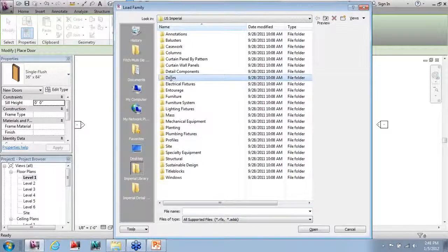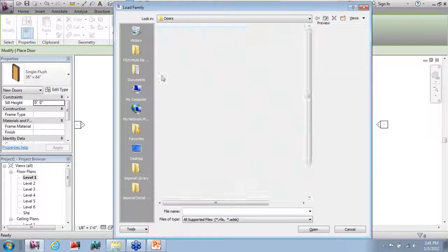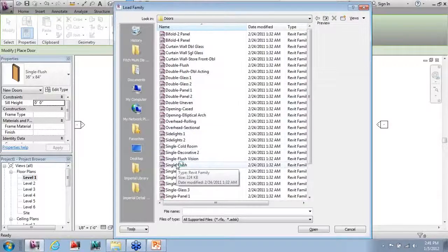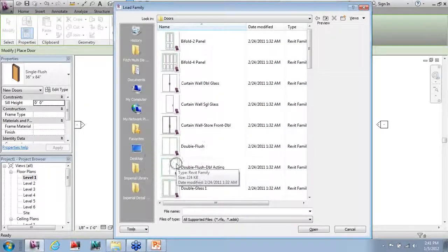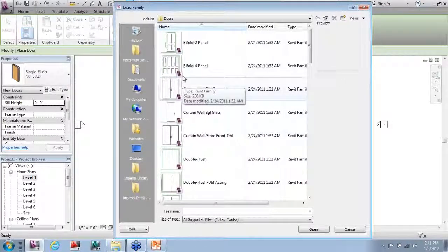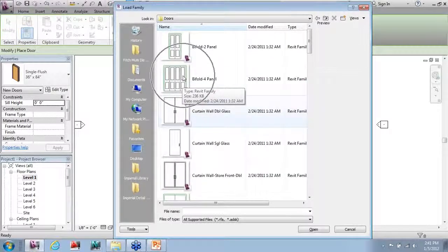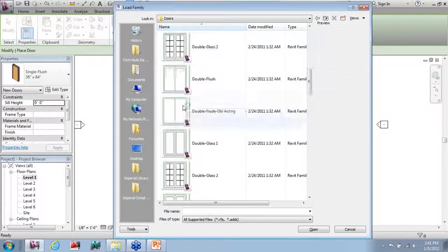You'll notice right now that our Imperial Library has some really great features available to it. As an example, if I were to go ahead and select the Doors tool, I would notice that I could see all the different doors that are available to me. For those of you using Windows 7, a great feature, and this is not an Autodesk feature, this is Windows 7 in general: if you hit the Control key and you actually wheel forward with your mouse, it allows you to get a little icon of any of the content that's available to you. So just by holding the Control key and wheeling in just slightly, I can actually see all the doors that are available to me.